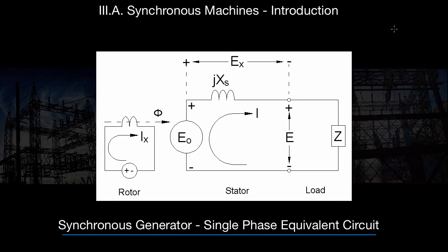Essentially, think of it like a backwards motor. If this was a drawing of a cut sheet of it, cut in half, our stator would be this section right in here. And then our rotor, I'm going to draw it solid just to make it different. The rotor spins inside the stator. So the first thing we do is the rotor has a DC voltage right here. So this is our DC voltage. And what that does is it puts a current, I of X, on our rotor windings. These are the windings here in our rotor.